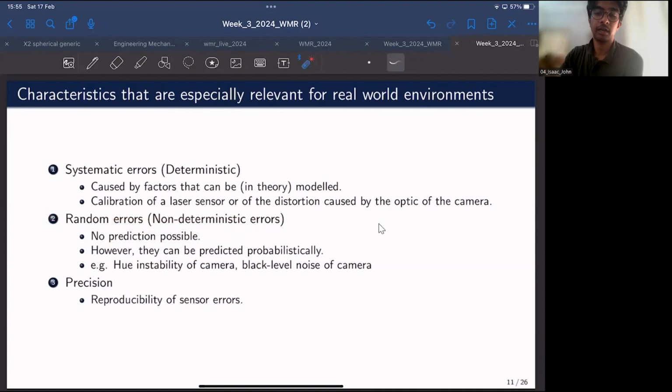However, we can model them probabilistically, and that too subject to some assumptions. You will see how these sorts of errors can be modeled, and how they propagate through the model. Propagation in the sense of how the errors in sensors propagate to the measurements, or to the exact x, y, theta location of a robot. We will see error propagation in detail in the next week 5 lectures.